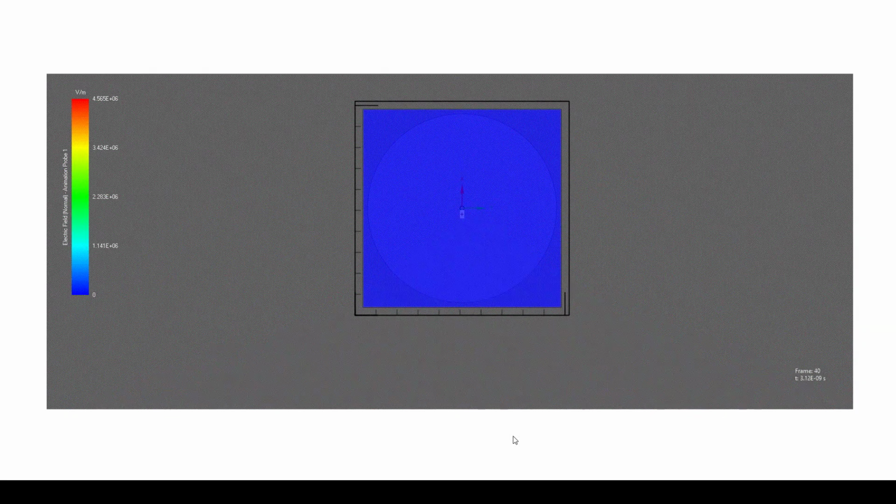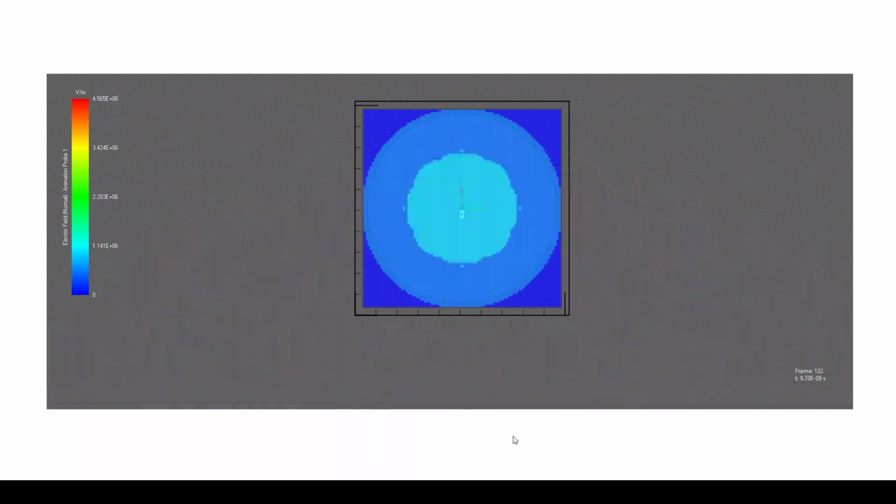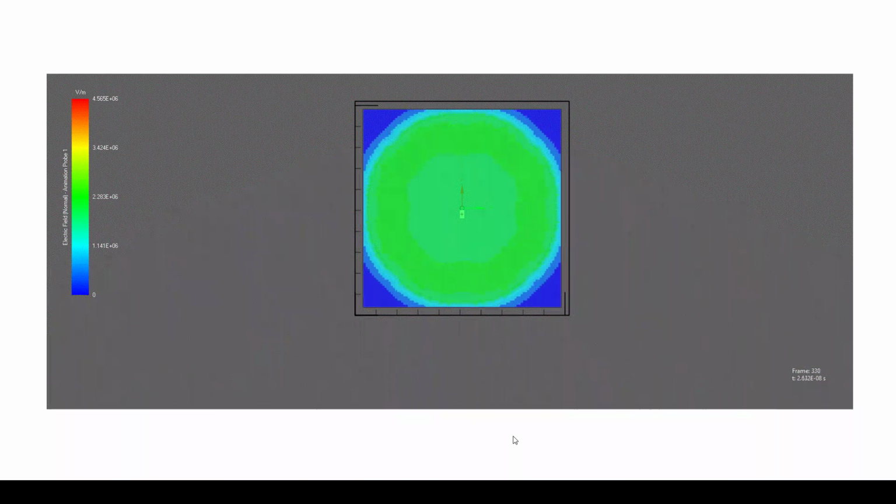In this GIF we see a charge build up on the electrodes, followed by a breakdown that initially occurs at the edges of the plates. The breakdown time, shown in the bottom right corner of the GIF, is 32 nanoseconds, which aligns with the voltage probe result.